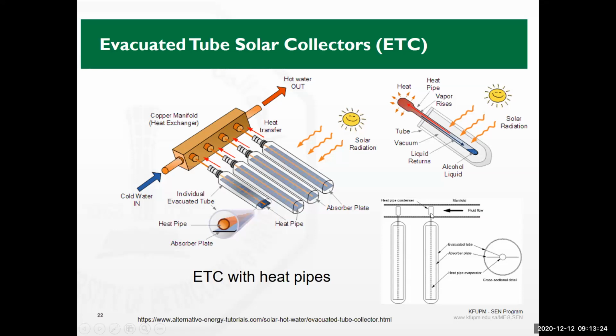Then the bulbs or the ends of these heat pipes are situated either inside a tank, so you can have a built-in evacuated tube collector with its own tank, or you have a header here where basically the flow of water or air, the fluid in general, is passing in. These units are always hot because when they condense, they will go down. It's a very quick process. They will go down, they're heated by the sun, evaporated, going up. So it's always a source of heat for the water which is passing through.